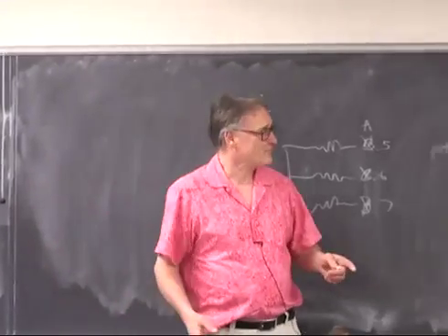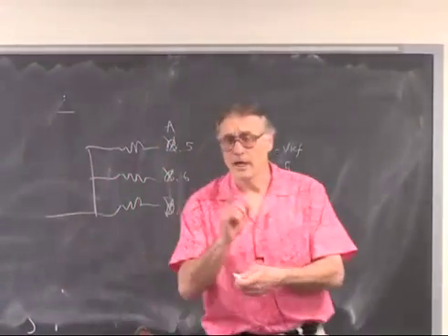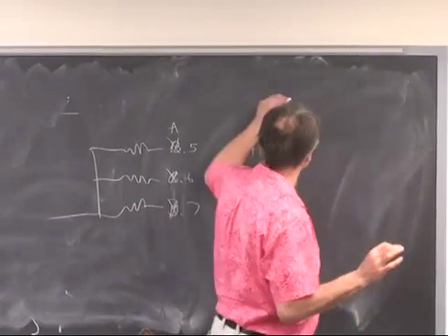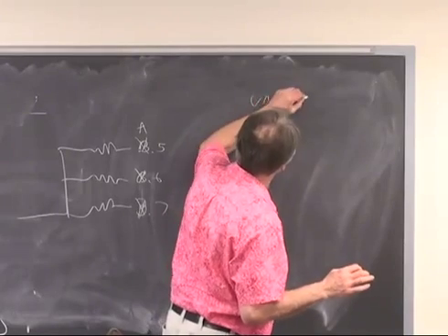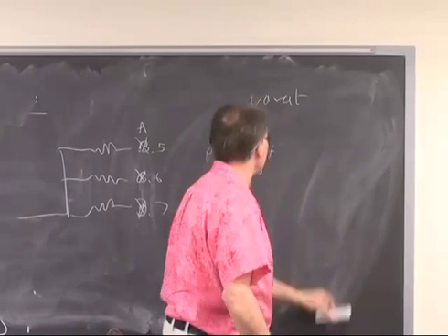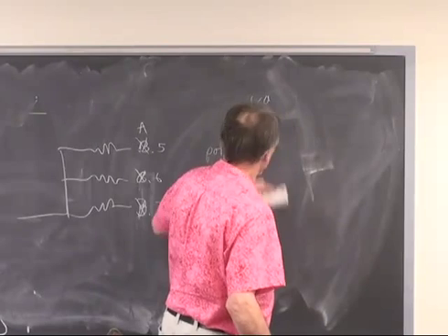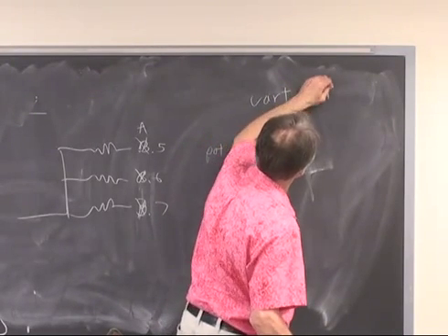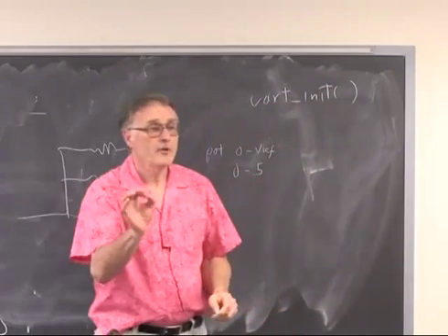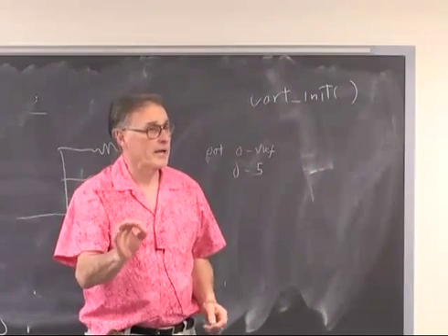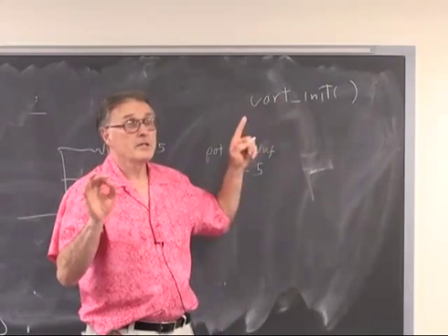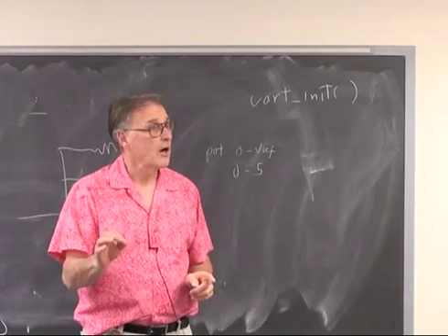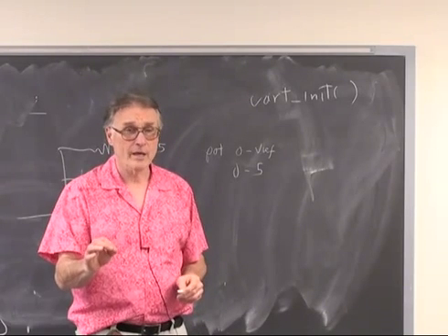I like it. The one problem you've got to look out for is that if you execute UART init, and never do a printf, D0 and D1 will not be under the control of the general I/O port pins.